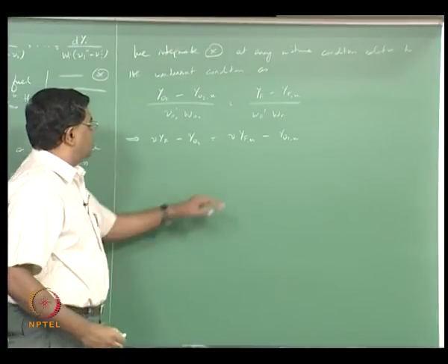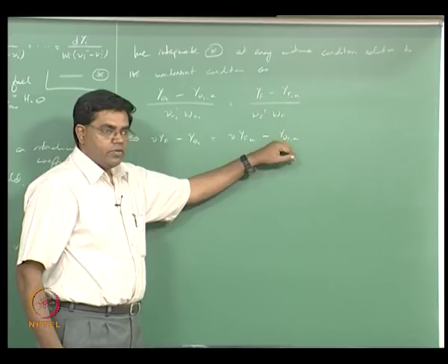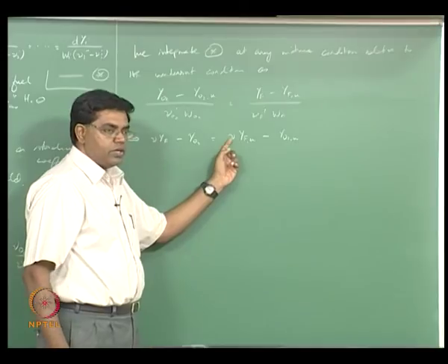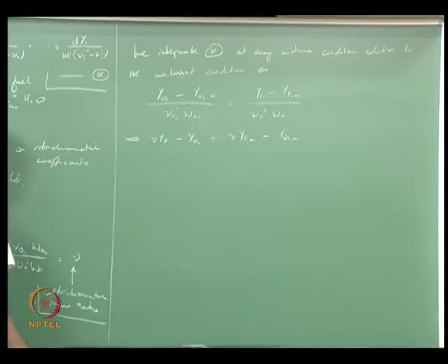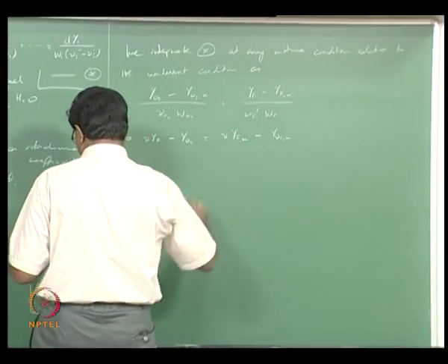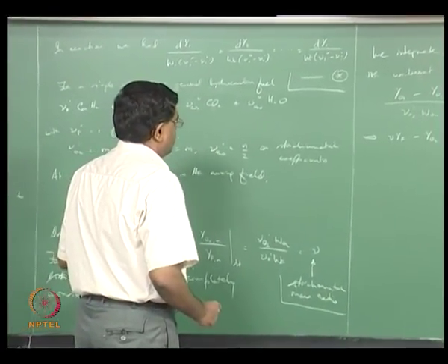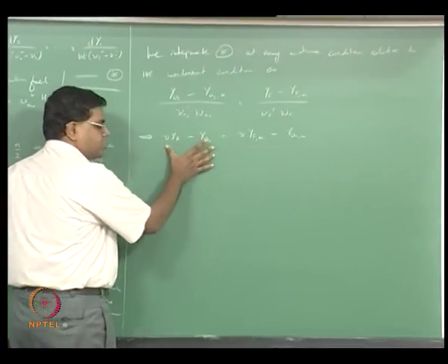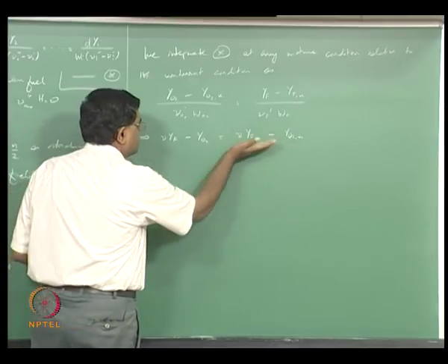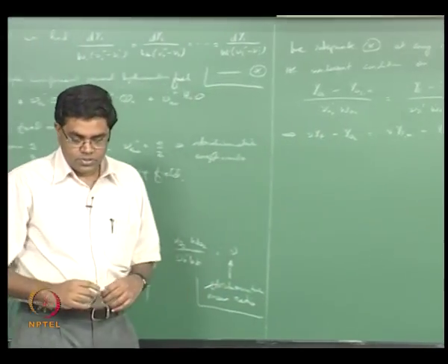You started out with unburnt values YFU and YO2U at a point in the mixing field in a proportion with a nu here, right, and that is the same even during the reaction between the two. That's essentially the idea. Whatever the unburned values are, that difference is what is preserved.